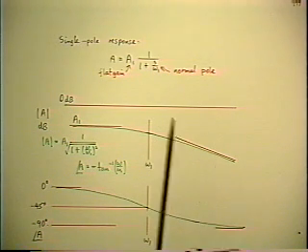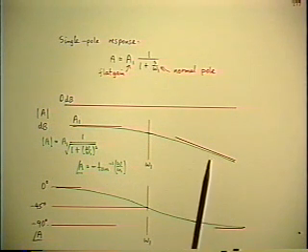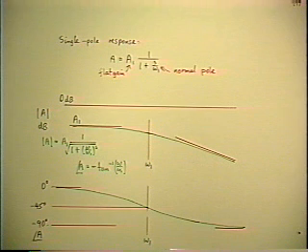If the frequency goes up by a factor of 10, the gain goes down by a factor of 10, which is 20 dB for a factor of 10 or a decade of frequency. I don't think there's anyone here old enough to remember the old-fashioned way of expressing that, which used to be minus 6 dB per octave.